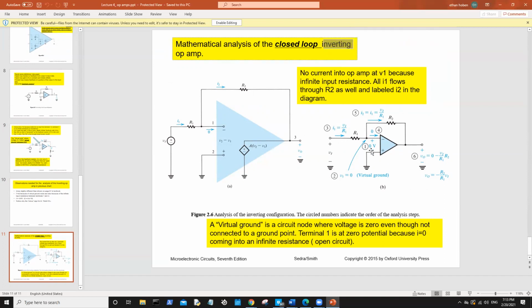So I take it if this were headed here, it wouldn't be inverting. No, that would mean it's positive feedback. I think if it's non-inverting, then the power and the ground switch places. Yeah, I think so. I was going to say, the textbook talks about positive feedback. If they were connected between terminals 3 and 2, you would have positive feedback. But this says it generally causes the op amp output to saturate rather than providing a stable gain, which is why you use the negative. So positive feedback sucks. Basically, that's what I'm getting from the textbook.